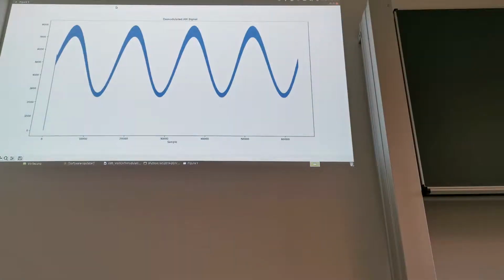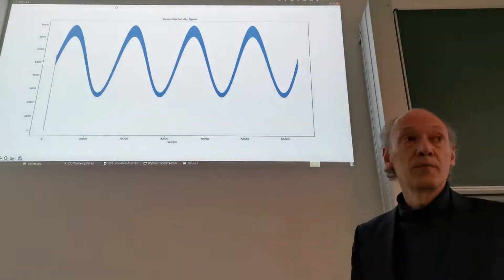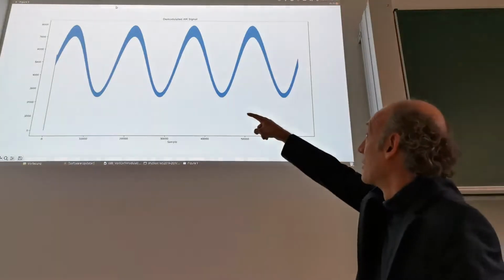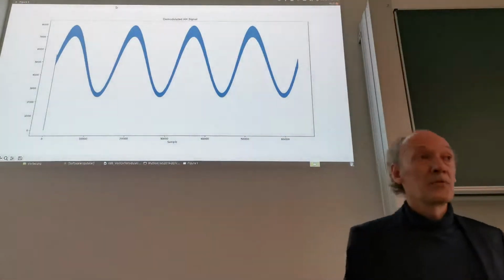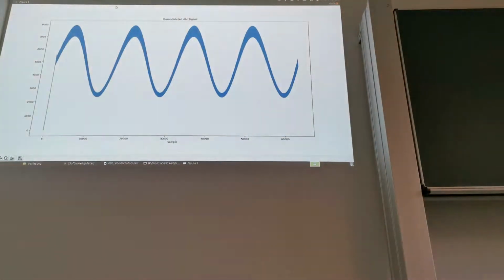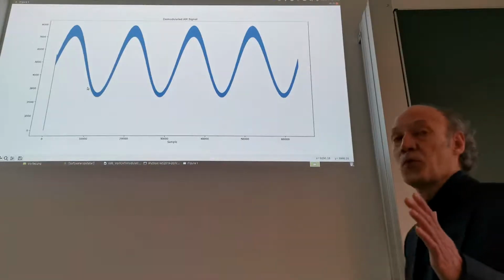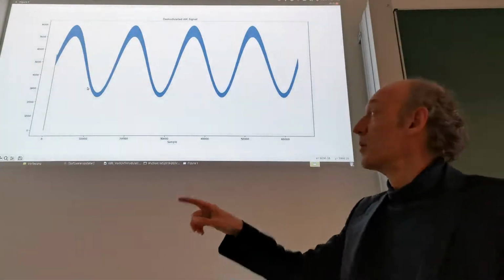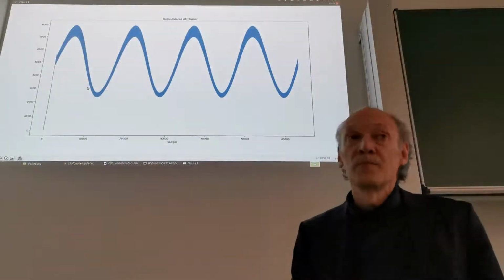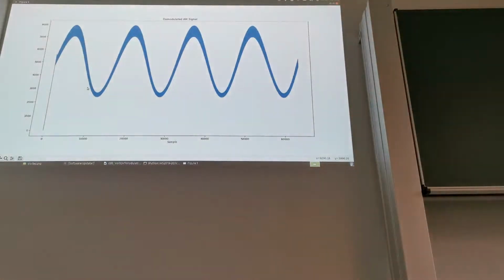And you can see it basically looks like the cosine part alone. Again, this smeared sine function with an offset. This offset from 0 comes from the amplitude modulation. Remember we had this 1 plus 0.5 times the tone, and this is what we see here. The offset is the 1. Makes sense?